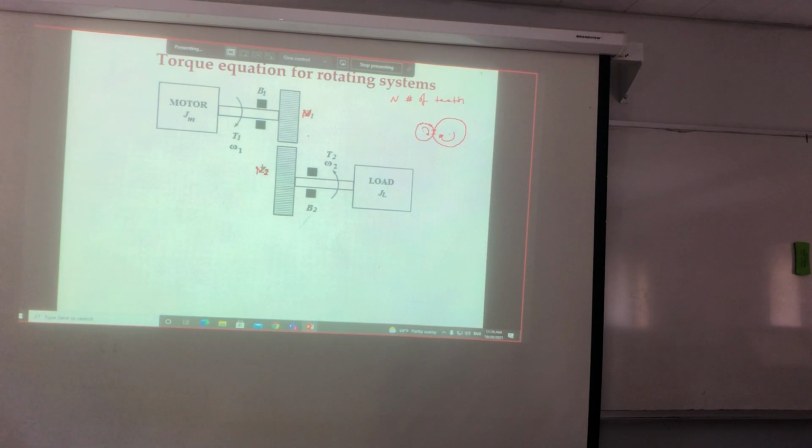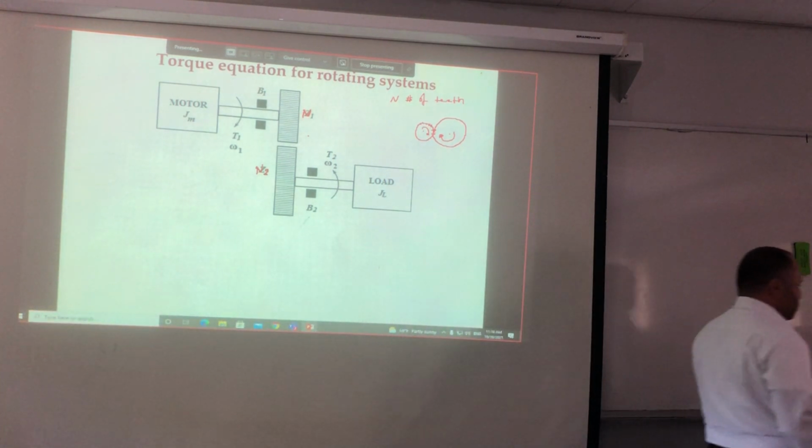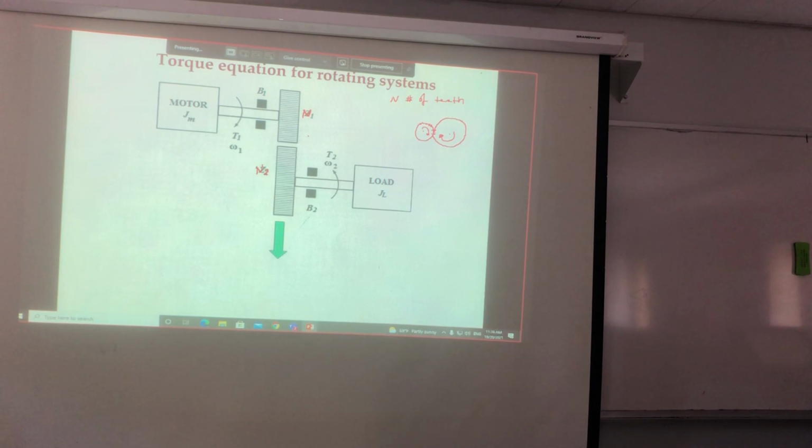Now, how can I model the system? At the end of the day, I need only a two-mass system, which means a machine engaged with a mechanical load with equivalent inertia and equivalent, let's say, viscous friction. How can I do that? You know that if I need to write the mechanical equation, which all of us know, it's J dω/dt plus bω must equal the summation of the torques, let's say Te minus Ti.